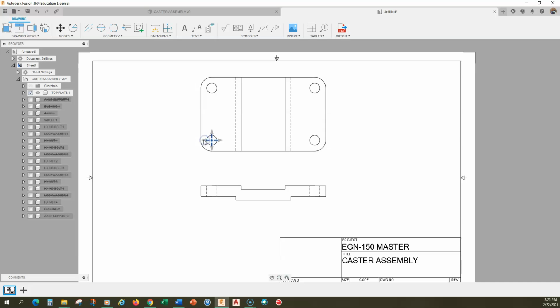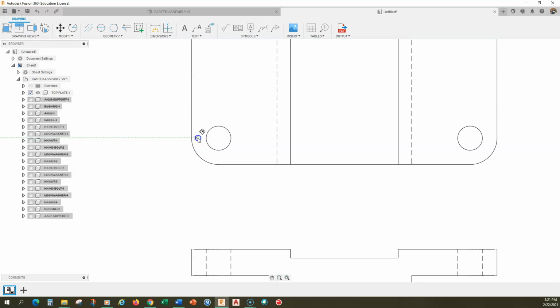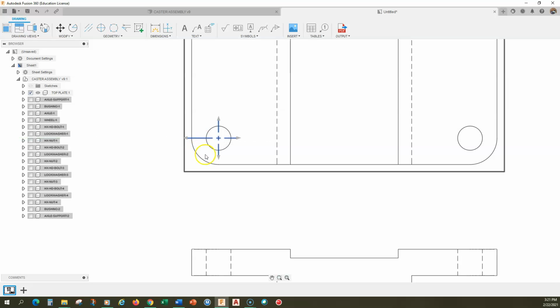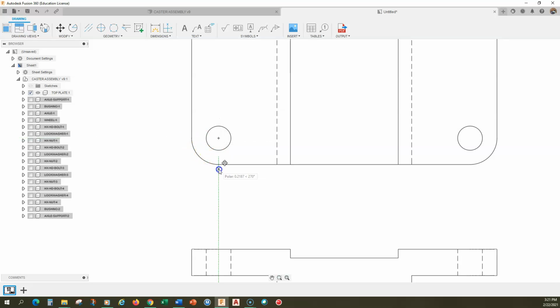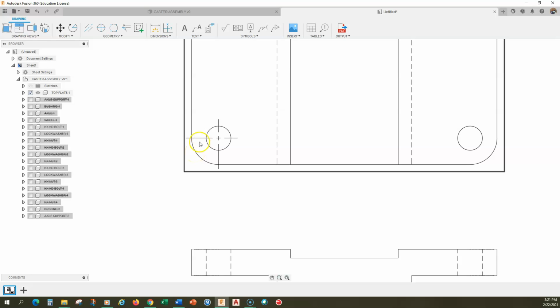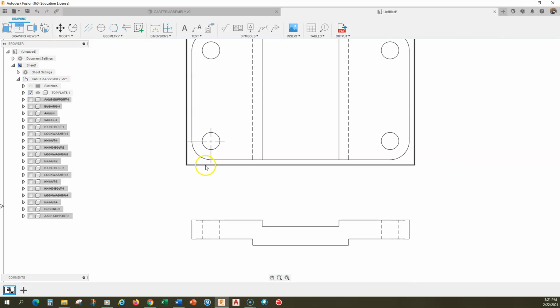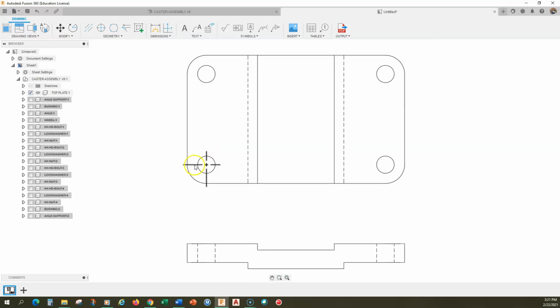And actually, I want to stretch this out. Now I'm going to zoom in here. I'm going to stretch this out like so. All right. Just a little bit beyond. Now, in the CAD standard, we talk about the extension beyond the edge that this is supposed to have. It should be 0.312, or I think 6 millimeters, but we're not going to worry about that. That's really something that we can do in AutoCAD. Right here in Fusion, we can't really keep track of that distance real easily.